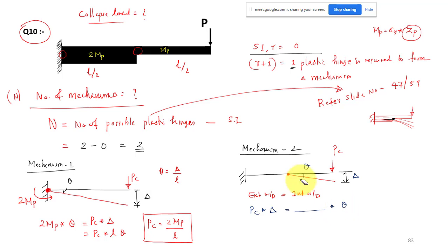But here at this junction, this part I have 2 MB, a larger cross section. The capacity of this section will be higher. This section has less capacity, you can say half. This MB has less capacity, and this has more capacity, 2 MB, and this section's capacity will be just half of this part. That means if you keep on increasing the load, where will your plastic hinge form? At this junction, one side I have a weaker section, that is MB, and another side a stronger section.